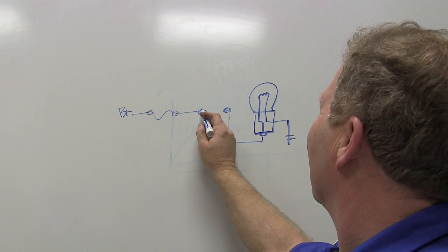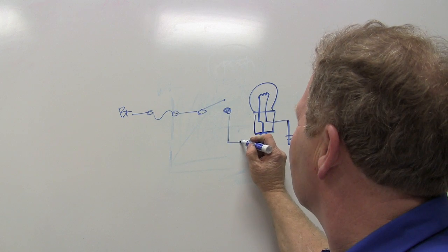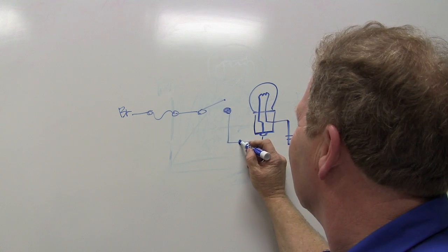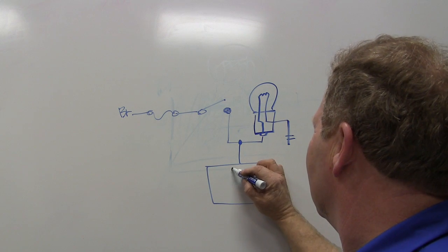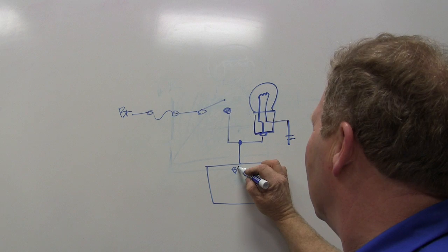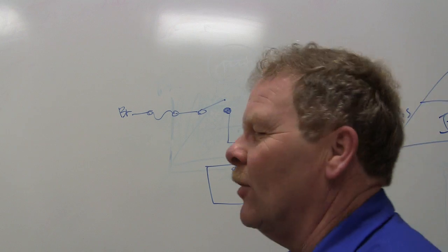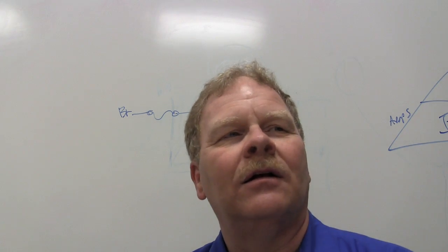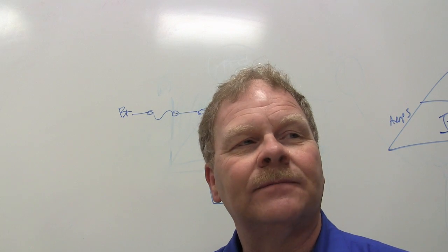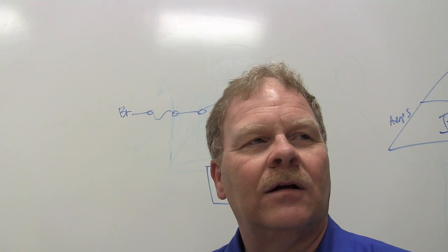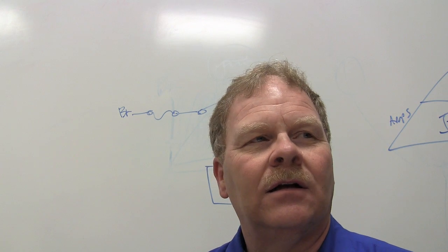this switch right here, when it's open, my cruise control is looking at that brake. And what is it seeing there? What is that cruise control module seeing there on that line when you don't have the brake pressed? It means that the brake is not pressed. I know, but how will it know when you press the brake? What's it looking at? Whenever it closes.